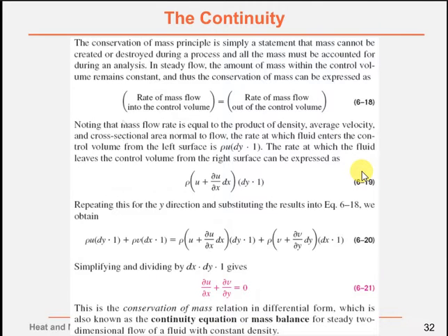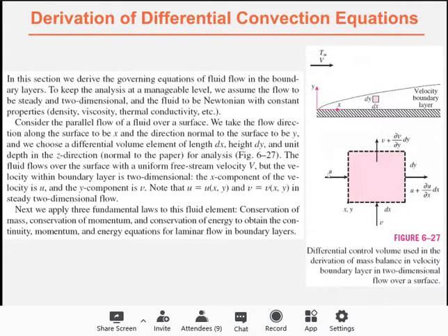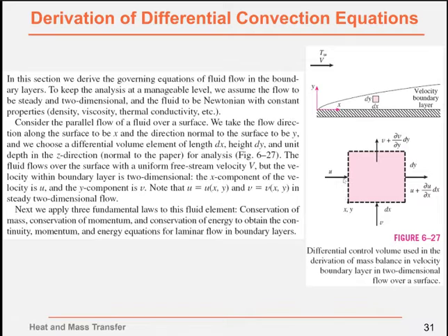And to apply the conservation of mass principle is very simple. The rate of mass flow into the control volume equals the rate of mass flow out of the control volume. That means this is the inlet, this is the outlet.